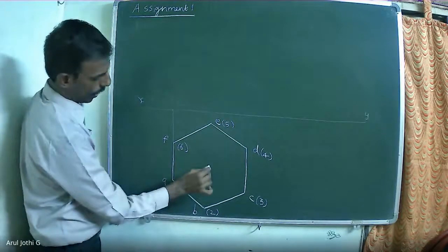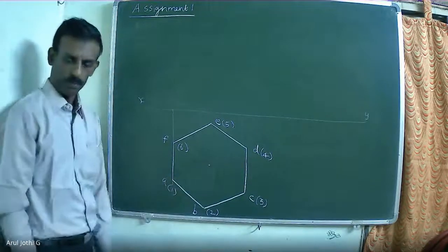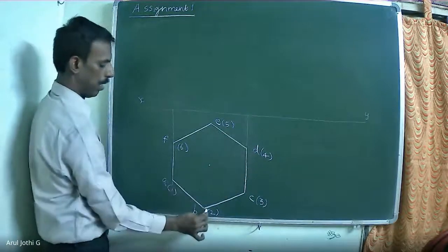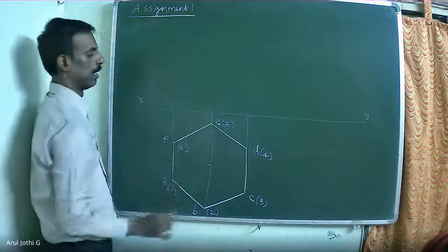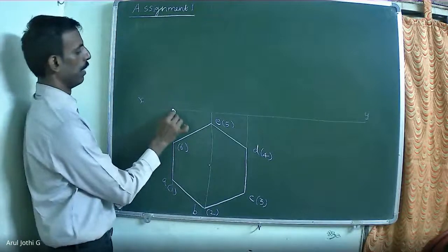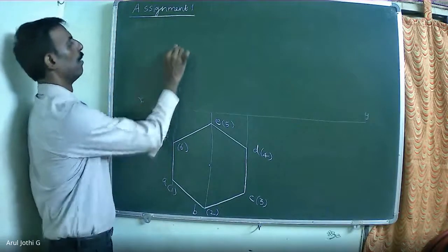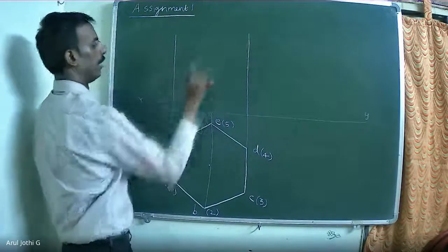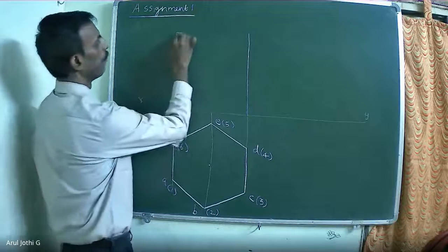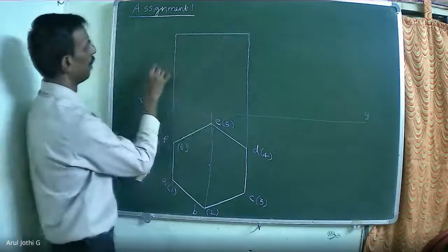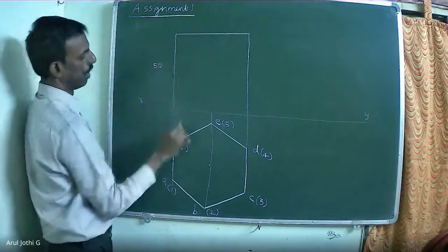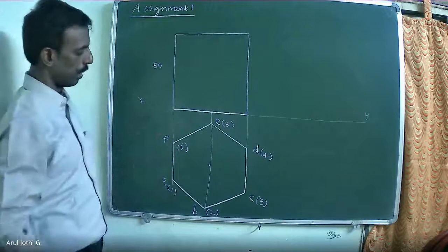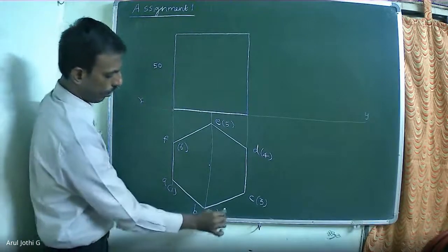Now, the axis point will be available in the middle layer. So, draw the projector lines. Axis side is given as 50 mm. For the given axis side, you draw the vertical line. The top base will be available here. The base is available, that is resting on the ground in the initial position. Now here, when you look in front view,